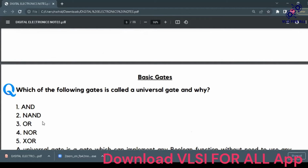NAND and NOR are used as universal gates because every circuit in the world, the circuits used in a processor, RISC, UART, or any circuit, can be implemented using NAND and NOR. Even when we use Verilog, the generated netlist consists only of NAND and NOR gates. Every gate can be implemented using NAND and NOR gates. That's why both are universal gates.